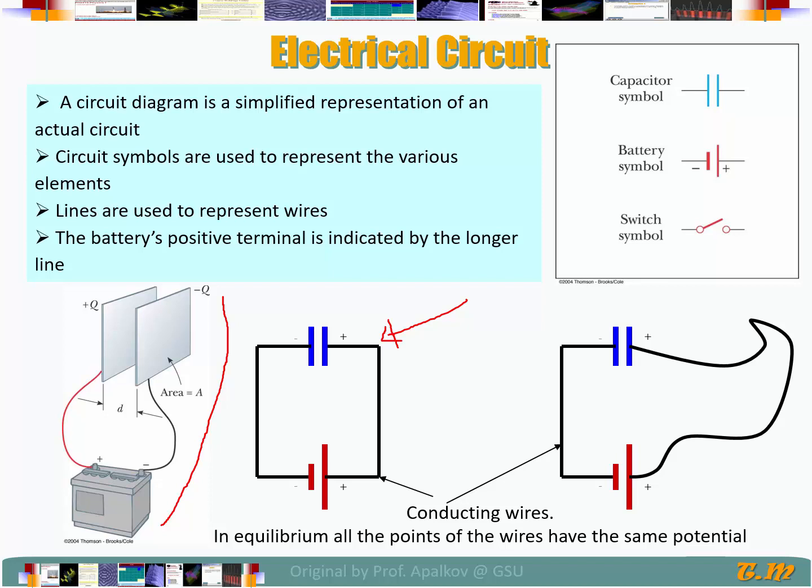Here are some symbols for a capacitor, for a battery. For a capacitor, sometimes we are going to have it look like this, instead of having them parallel, to represent other capacitors where they are not necessarily parallel plates, like electrolytic capacitors. Usually we do something like this. And for a battery, sometimes trying to represent that we have multiple cells, so instead of having it just like that, we might have 2 or 3 series of small and large bars.